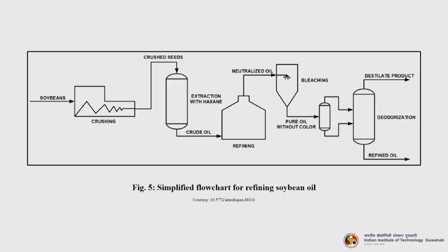Then the neutralized oil goes to the bleacher, where bleaching takes place, and then whatever you get is pure oil without color. Now, this is finally fed to a distillation unit, where we get the distillate product and refined oil. So, this process is actually called deodorization.